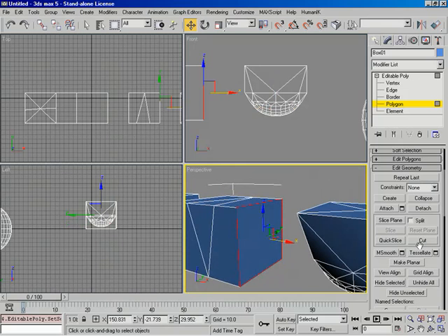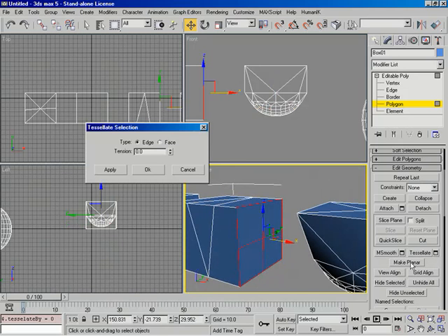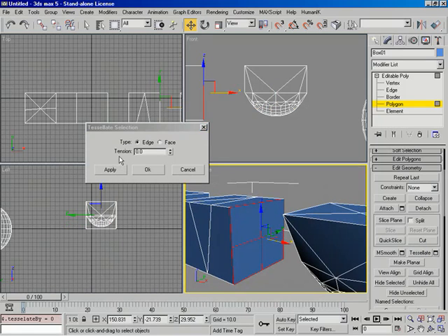What I want to do now is show you tessellate. I'm going to go ahead and open up options on it. I think it's important to have options from the very beginning on this. And right now, the type of tessellation is edge. What that means is all of our corners right here on the selected polygon, we're cutting all of their edges in half, and that's where we're tessellating from.